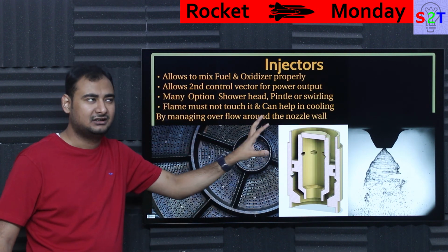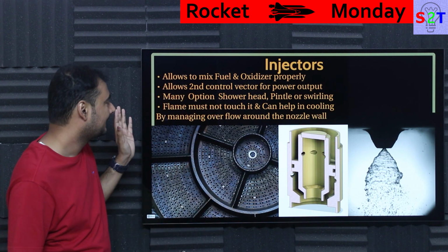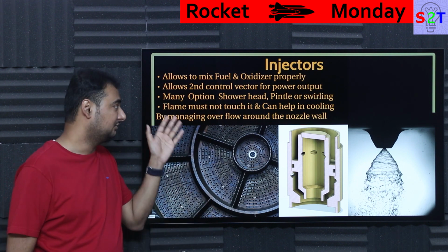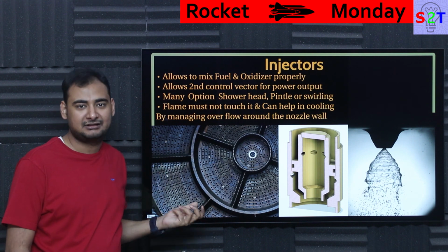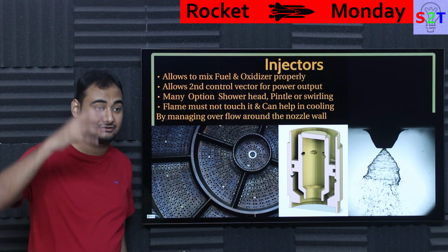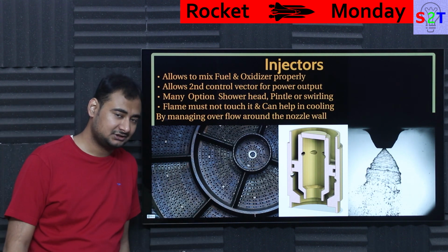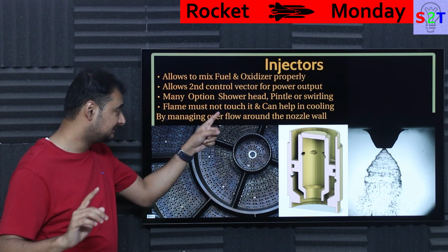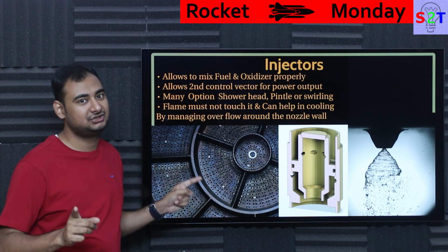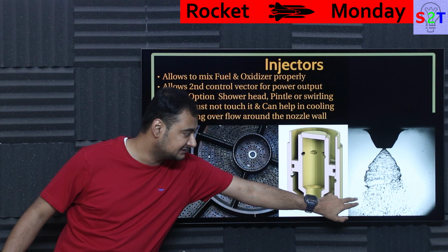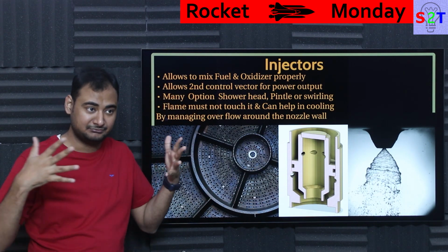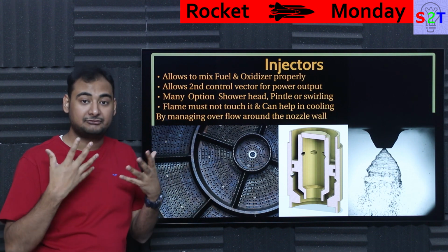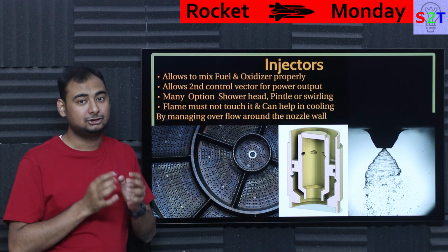This is a very complicated issue, and there are many options. Now you have the shower head, which, if you are like, wait a minute, that sounds like a shower head. Yeah, it is a shower head. People have tried to actually make rocket engines out of actual showers, and it has actually worked. Again, not the most efficient system, because this puppy defines your combustion efficiency. Meaning if this part is happening properly, if you are properly atomizing your fuel, if you are properly mixing them together, and its combustion flow rate is stable enough, then you're gonna get a good effect.